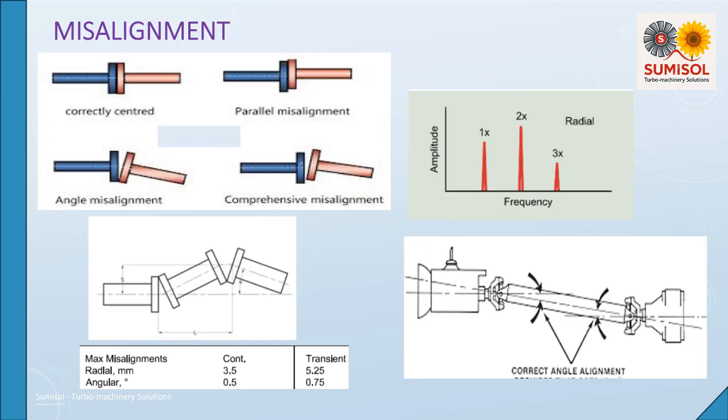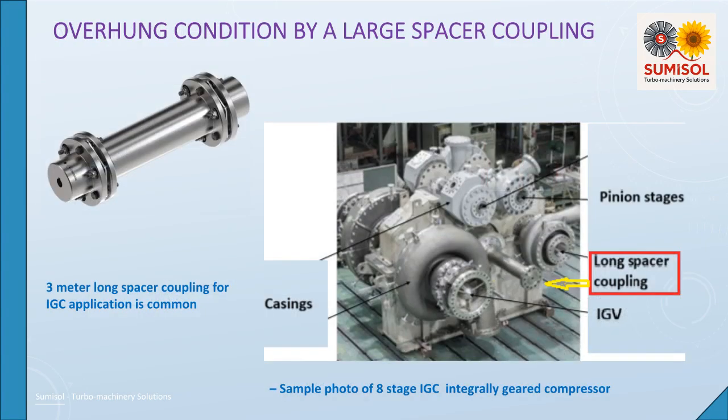coupling is flexible. A long or heavy spacer tube extends the coupling's center of gravity, CG, away from the machine's supporting bearing, resulting in a large overhung moment. This configuration, often used to allow for maintenance without moving the driver or driven equipment, spacer-type couplings, introduces several risks, primarily centered on rotor dynamics. Excessive overhung mass/moment can shift the machine's lateral critical frequency closer to the operating speed range, causing high vibration. The weight of the spacer can create significant shaft deflection.